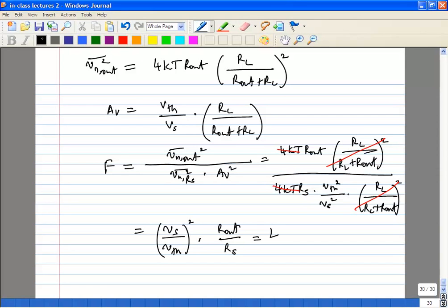Okay. So this is a very important result for us. If you're inserting a filter, it automatically ups the noise figure by the same amount as the power loss. So what does this mean? Remember our receiver, before the LNA we put in a band select filter. The loss of the band select filter should be as small as possible, because it directly adds to the noise figure.